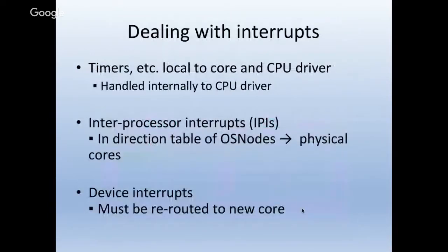Also, I want to talk about interrupts and how we can deal with them. In general, interrupts are distinguished into three types in the system. First, local interrupts handled by cores and the CPU driver, like timers, and interprocessor interrupts which are sent between OS nodes, and also the device interrupts.